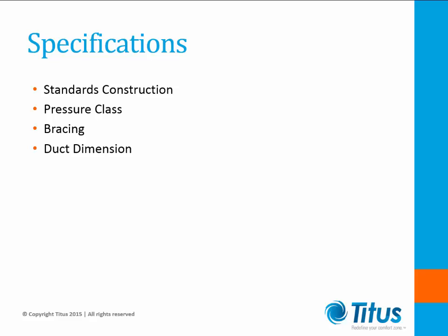Duct dimensions on drawings should be detailed, how they are designated on the drawings. In most designs, the ductwork sizing on drawings are inside clear dimensions and do not account for liner or bracing. This should be clearly identified either in the specifications or the drawings. This will allow contractors to provide accurate pricing for the project and ensure the design intent of the project is met.